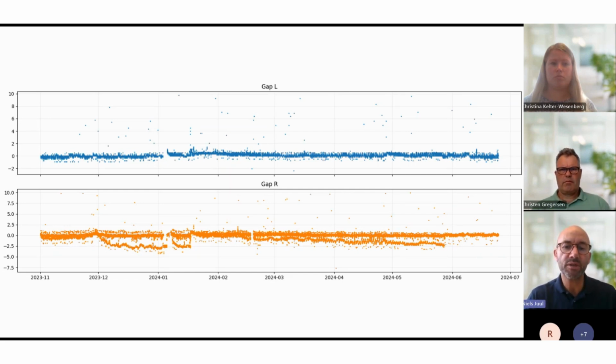And this is also where gap monitoring not only monitors the gap between the stock rail and switch rail, but also monitors and detects different other failures that might not be able to be seen due to normal maintenance procedures. So this is some added benefit that can be provided by a system like this.